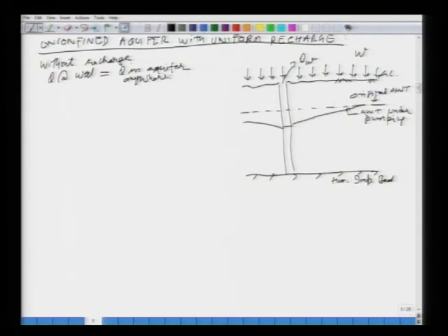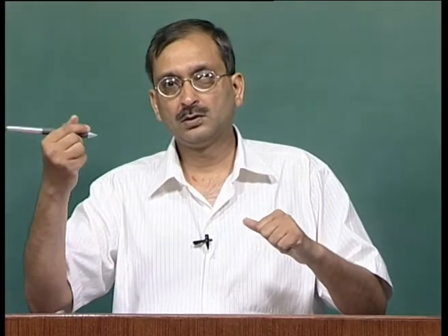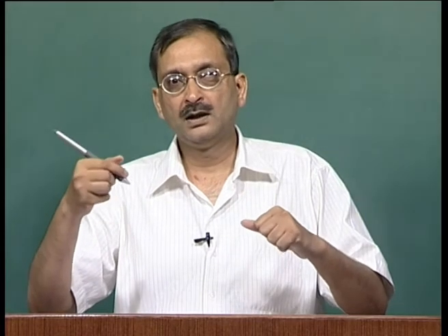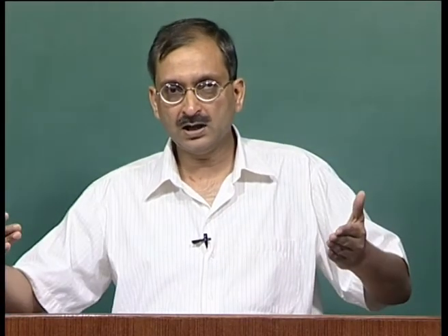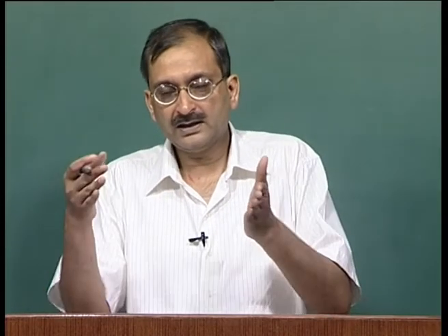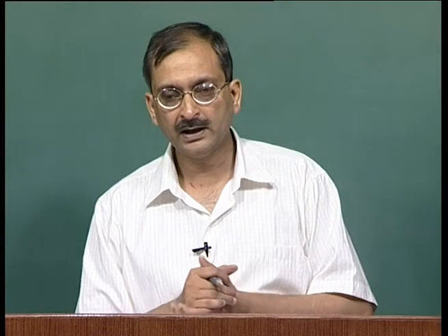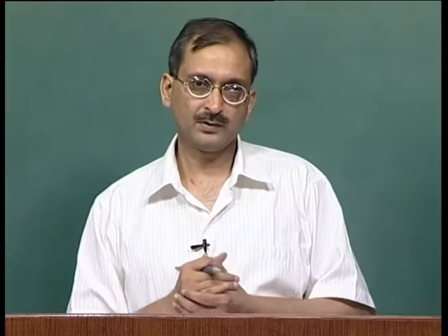What we are saying is that if you have no recharge taking place, then the discharge we are pumping out, the Q from the well, is equal to the discharge taking place anywhere in the aquifer. In fact, that is the equation we had used. Q was velocity times area. We used Darcy's law and found out the cross sectional area. So, that is the concept we had used.